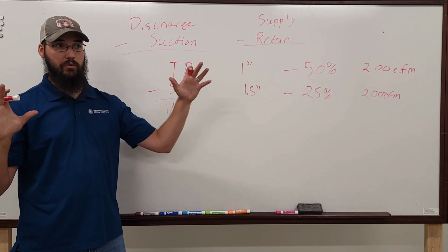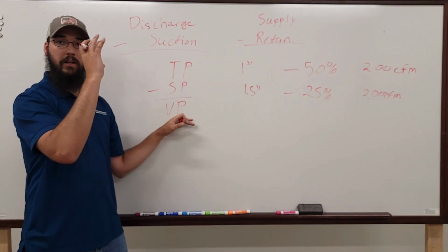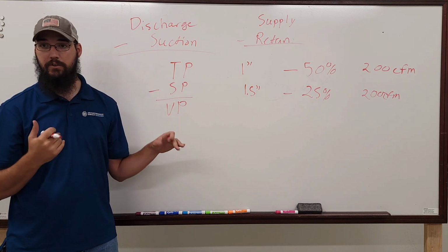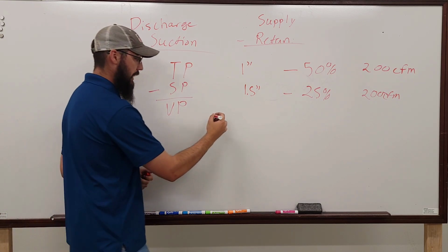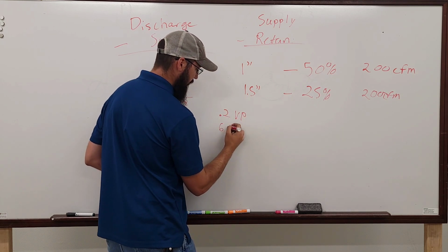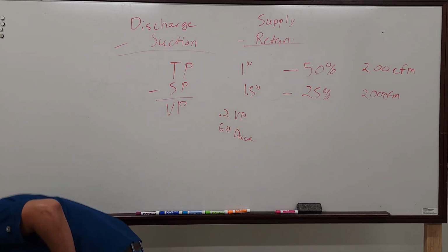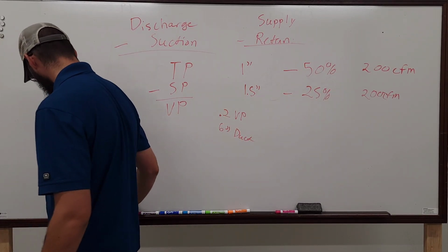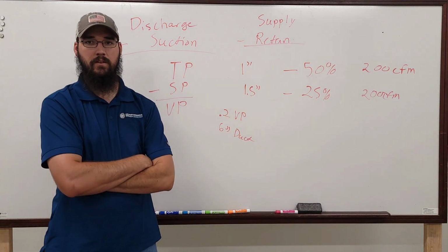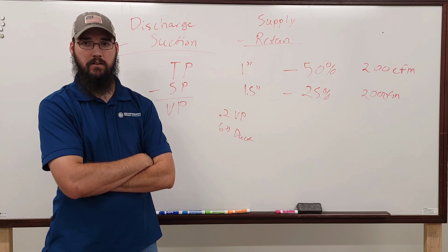So it's taking those two pressure readings, subtracts them to get velocity pressure, then it looks at the duct diameter on the incoming side, which is 6 inch, so if it has a 0.2 VP on a 6 inch duct. Static goes up as your static pressure, because that's part of your calculation of velocity pressure, correct? Yes. As static pressure goes up, how does that affect velocity pressure?